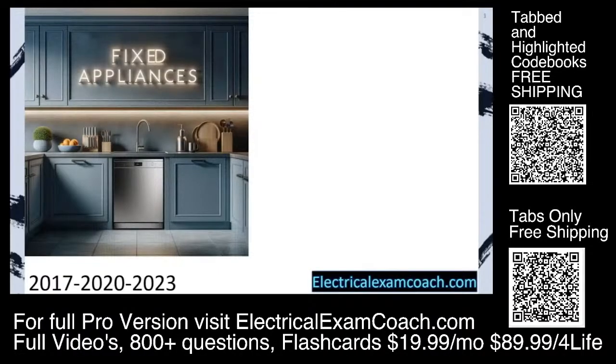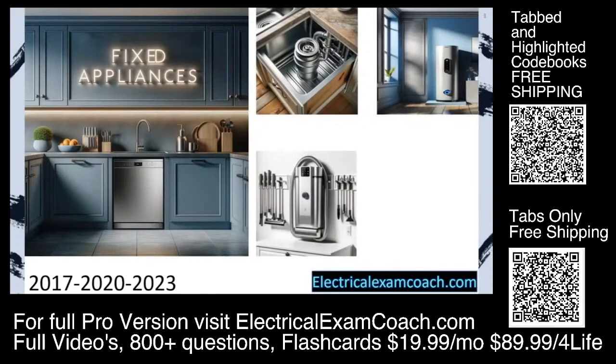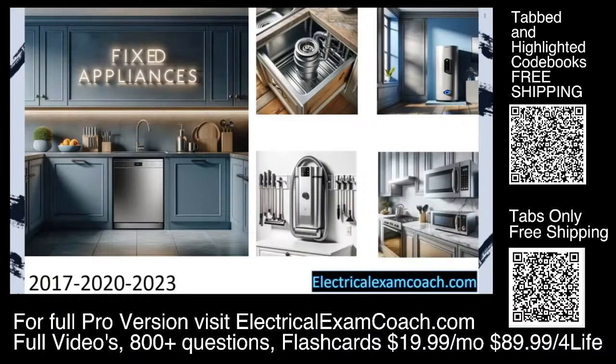Fixed appliances include things like dishwashers in this picture, but it also includes things like garbage disposals, water heaters, central vacuum systems, and microwaves, and pretty much any other appliance once it's fixed. You'll notice in this bottom right-hand picture that there's 2 microwaves. One is not fixed, and the other one is fixed. And when you fix it to the wall or fix it so it can't move, either with plumbing or mechanical vents or anything else, it now becomes a fixed appliance, and there's a special way that they calculate them when doing a whole home load calculation.